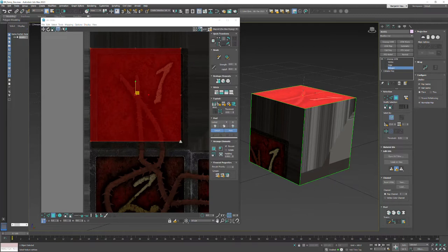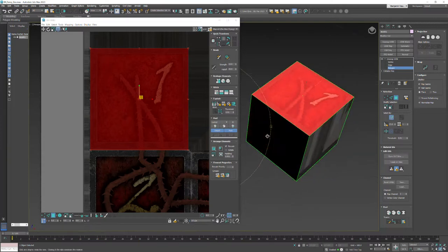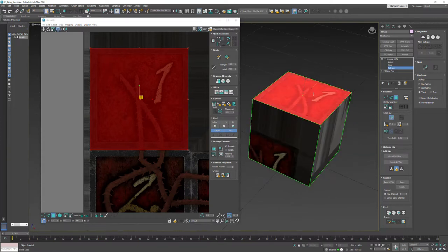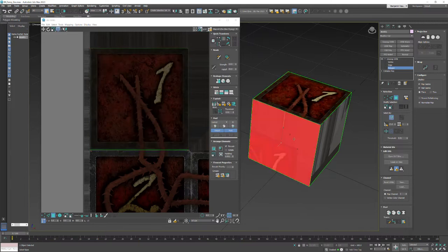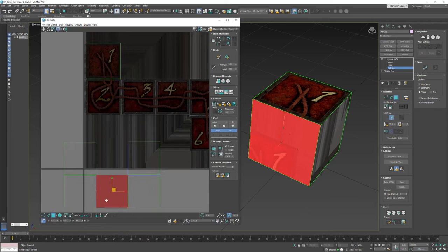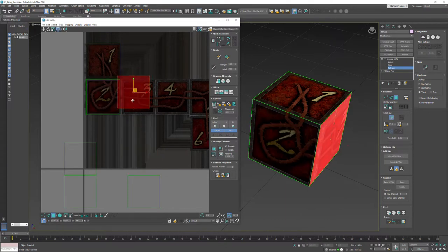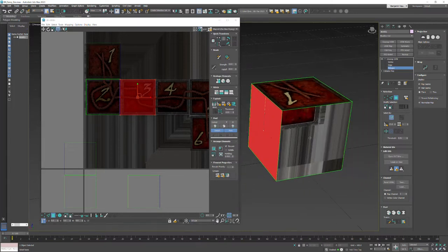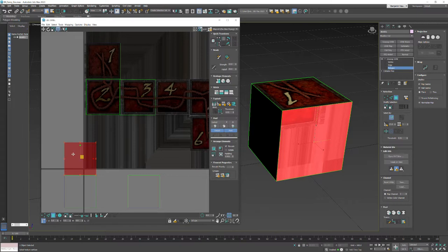Now I'm going to click and go into freeform. Freeform's usually the default tool that it's on. And you can always go down to orbit around to see it better. F2 will toggle the shading in here if that ever gets in your way. F2. So let's click on this box. And now I just want to make it so that this little vine wraps around. And so I'm just going to keep going through and grabbing these pieces. So it's pretty simple, just orbiting around, gets us used to working in 3D space.